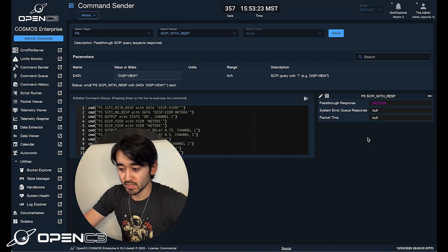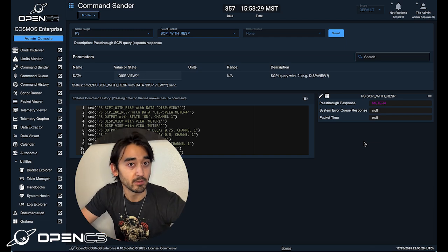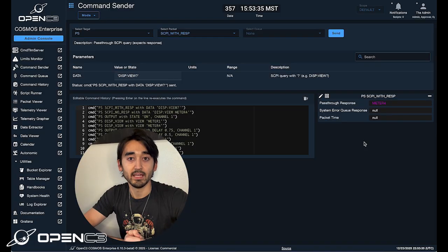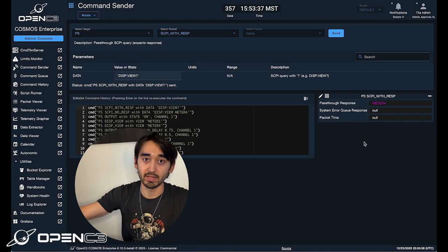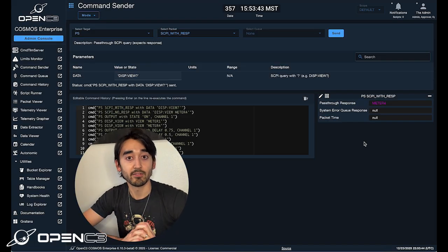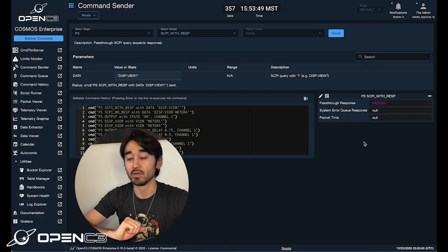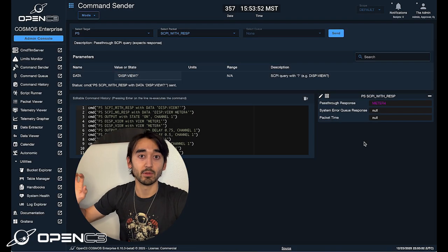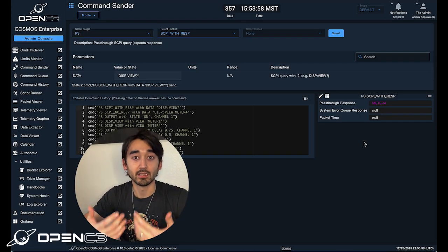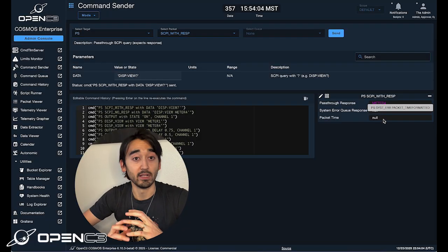So you might be wondering, hey, what is this system error queue response and what does that detail? What do you do when these commands to the power supply fail? Well, how the power supply tracks errors is that there is a queue of errors that are building up. And as part of our get status packet that is commanding to retrieve the status of the power supply, we are also querying for the error. If there's no error, it's just going to say +0, no error. But if there is an error, it gets popped off from the queue from the power supply and then added as a sub packet into Cosmos. So then that's a great way for you to look at the different errors that might be happening. And we are always going to be showing the latest error that occurred if there is any reported.